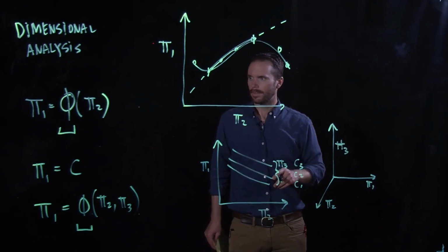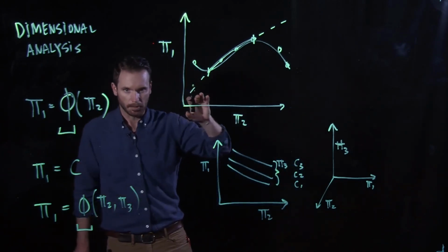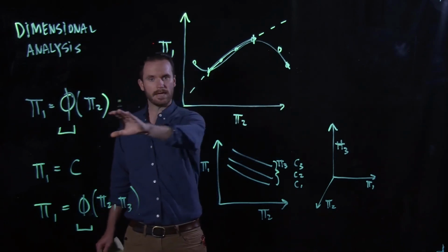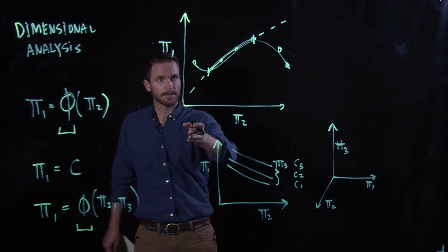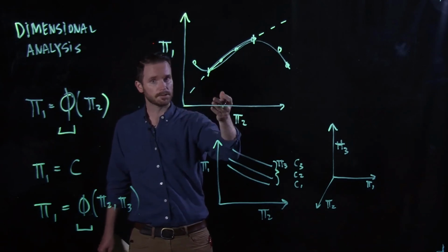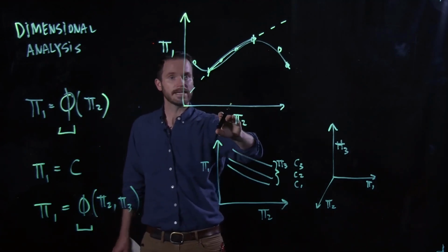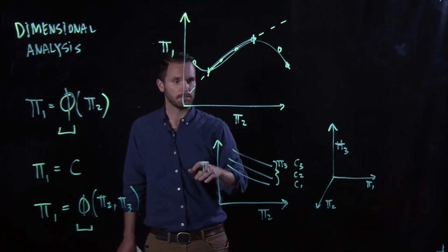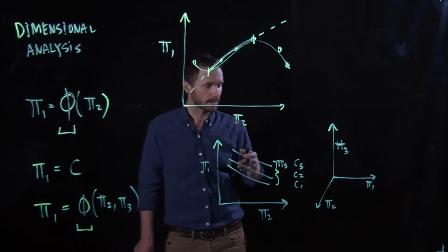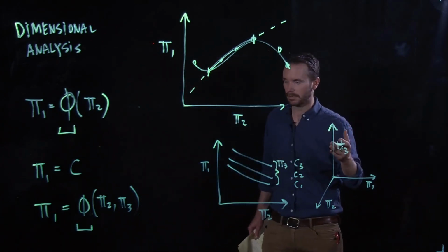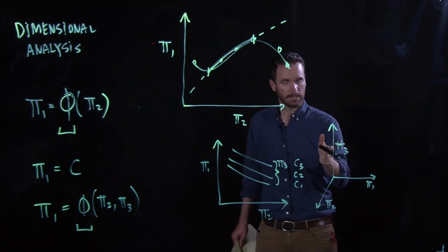So this is kind of the power of dimensional analysis. The ability to take a very complicated problem that is a function of many variables, simplify it down to a function of fewer variables that are dimensionless, and then be able to carry out experiments that are then extensible to other systems and other situations, so that you can take this functional relationship between these dimensionless terms and be able to gain information. Now, the next step in this is saying, okay, let's extend this into that concept of similitude that we introduced at the very beginning of this chapter. How do we use these relationships to move between a model and a real-world application?